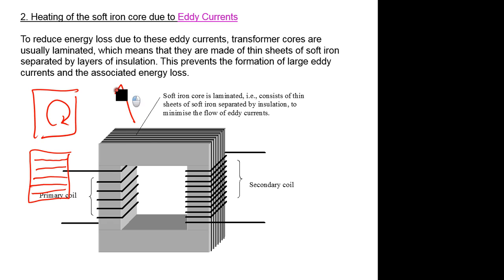You are looking from the top like this. The current looks like this. It's small and tiny, with only a small place to go. The resistance is huge, the current is small. So using P equals I squared R, the power loss becomes a lot smaller. These are laminated sheets which are not conducting. I can draw a not so small one so you can see the direction of current. Like that.